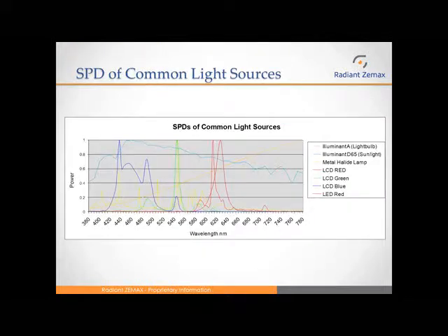All right, here are some examples of common spectral power distributions. And it's important to understand this because it affects the color calibration of our camera. So even though our camera doesn't measure wavelength, or imaging colorimeters don't measure wavelength, they still measure color and they still have to be calibrated. And those calibrations are dependent on the incident spectral power distribution.